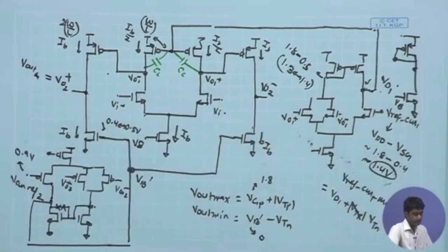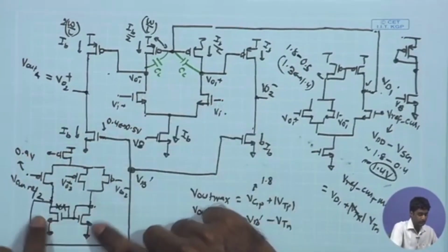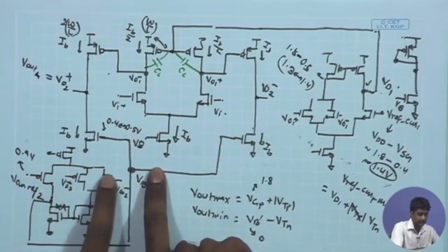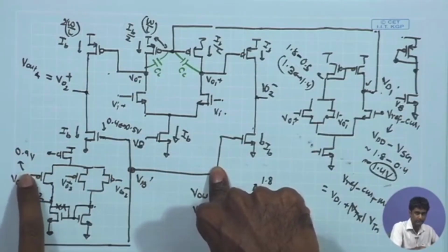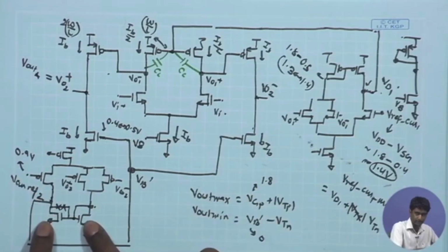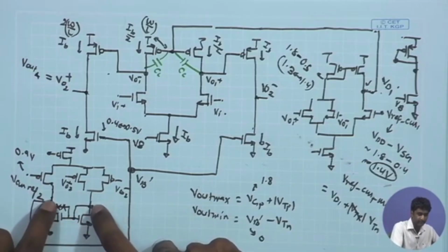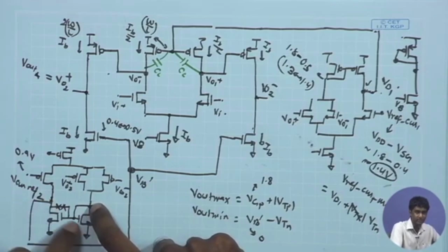And once again here we can see why we have chosen this NMOS load, because of the output DC potential. If I look at this as a differential amplifier with current mirror load, in the steady state condition in which the effective DC potential at the gate of this PMOS and the reference PMOS is same, we are going to have same current in these branches approximately, and as a result the gate voltage being same, the drain voltage of these NMOS devices are also going to be same, which is going to be equal to VGS of NMOS.